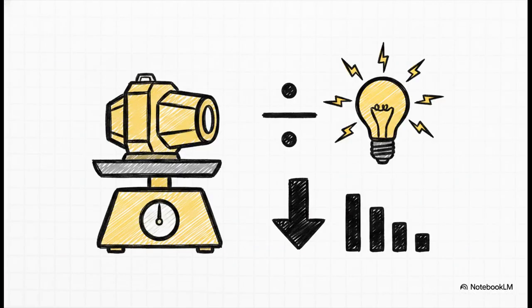And this brilliantly illustrates how simple the final math really is once you isolate the correct parts. You just take the mass of the top head in metric tons, again without the blades, and divide it by the rated capacity in megawatts. Your final reported metric is delivered in tons per megawatt, or TMW. It's that straightforward. And of course, the lower the number, the more efficient the design is at generating power relative to the sheer mass it requires.